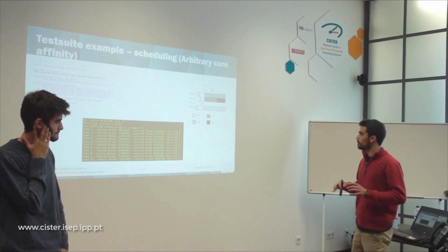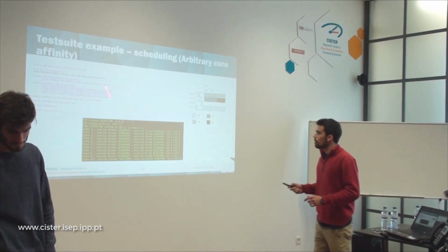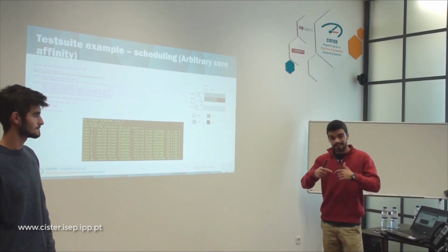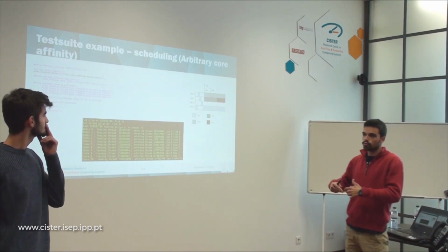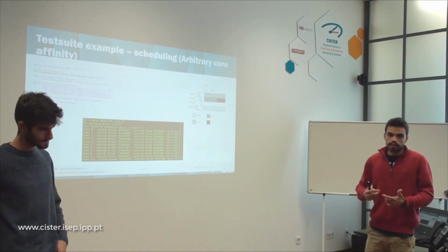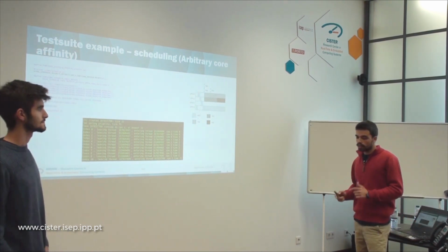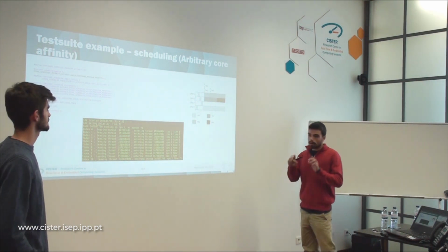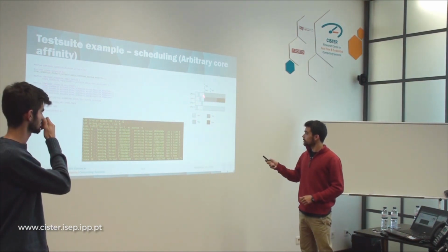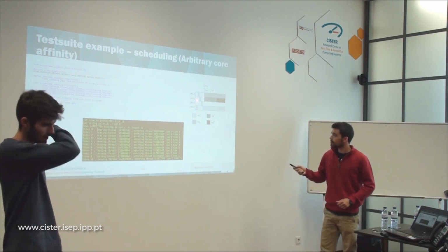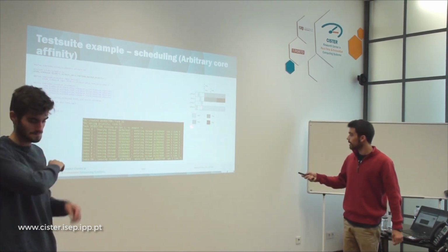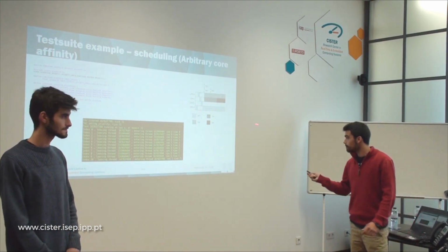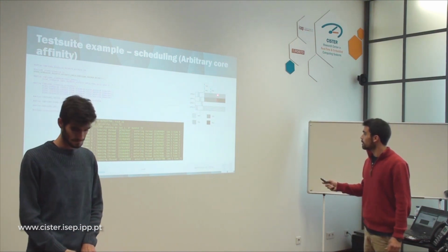So we created a really simple application, where we were going to play initially with the init task, that is the task that is configured to enter first to configure the application, the main thread of the application. We're going to play with it, moving it around from processor to processor, and so on. So here, our vision will be this one, initially, until here. We have the init task on the last processor, we're going to move it to the first, the second, the third, and then it's going to be back to the last processor.